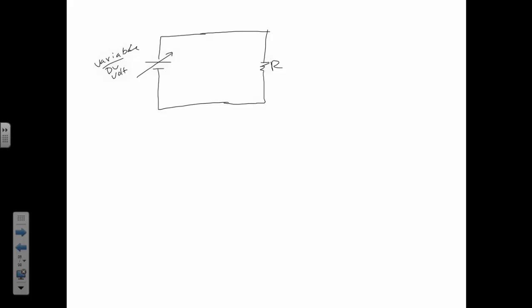So if I measure this, what do I got? 385 ohms. Ignore that decimal point there. It's supposed to be 390, but I have plus or minus 5% tolerance on this. 5% of 400 is 20. I can be plus or minus 20 ohms off, and I'm only off by 5. So I'm well within the 5%. I'm actually 1.25% off, low. So there's a little tolerance you can have on that.